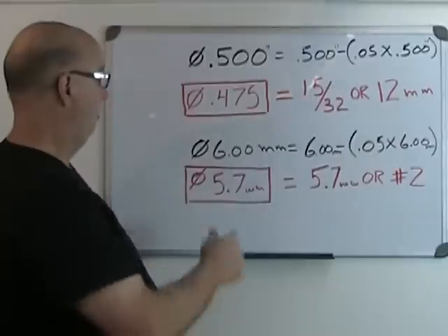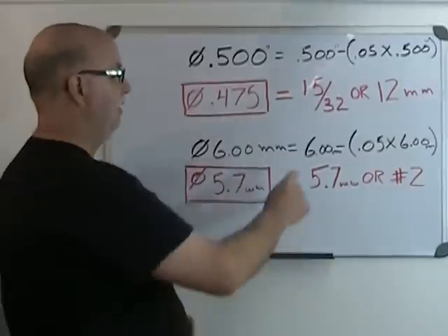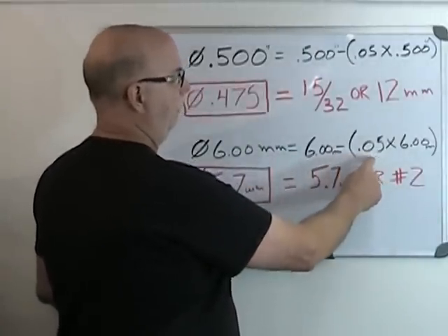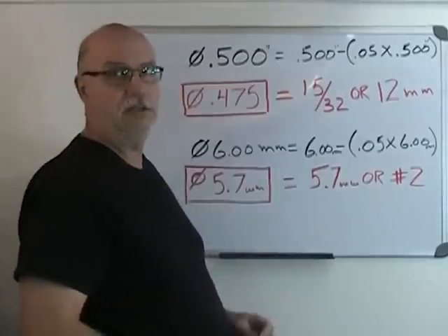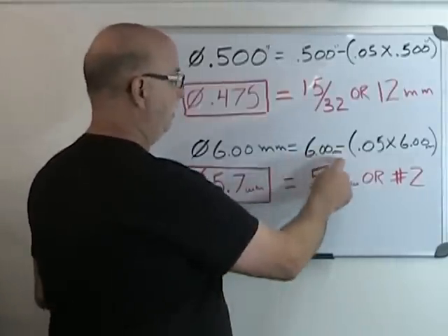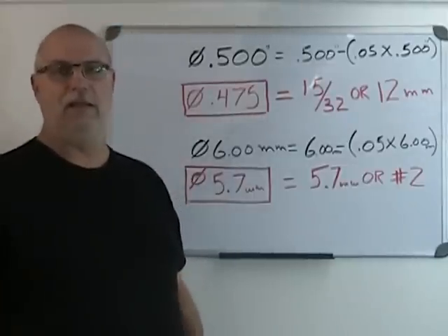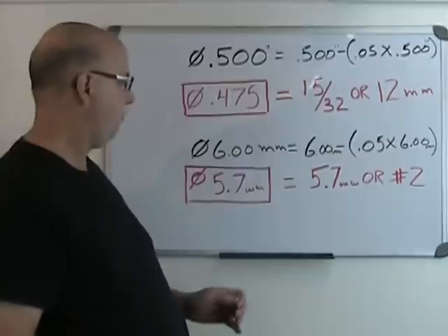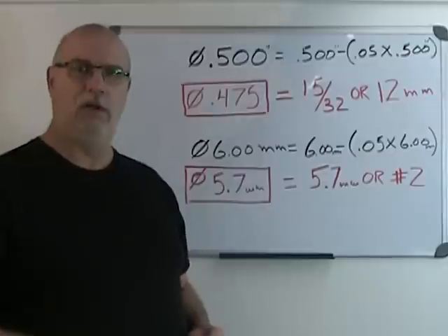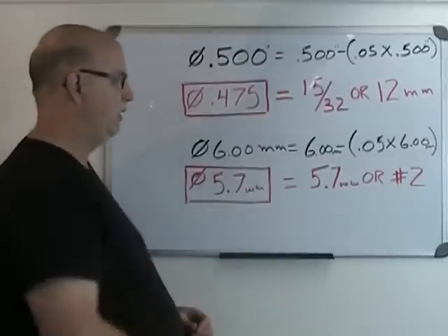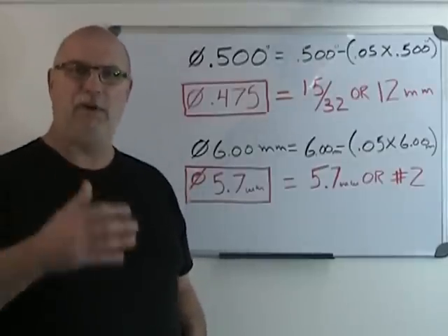Our second example here, well, we have a 6mm hole to ream, and for that we're going to do the same thing. 6mm minus 5/100ths times 6mm. That gives me 5% smaller than 6mm, and this subtraction here gives me my final result of 5.7mm. Now, we said two videos ago that you can have metric drills in all dimensions at increments of 0.1 millimeters. So if you needed to use a 5.7mm, well, that 5.7 is available. But it's not part of a standard set.